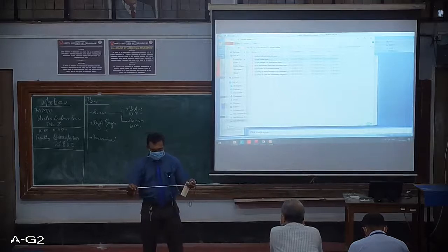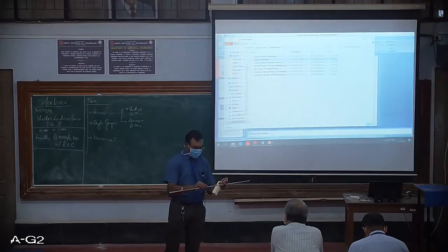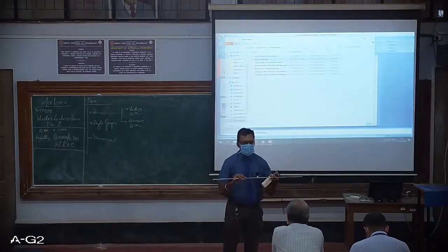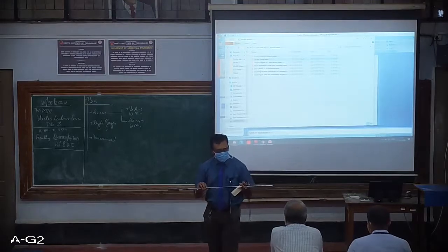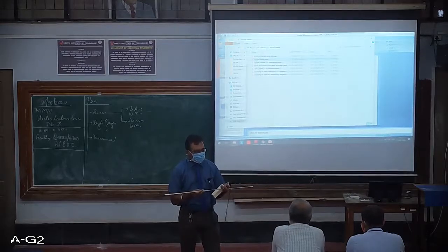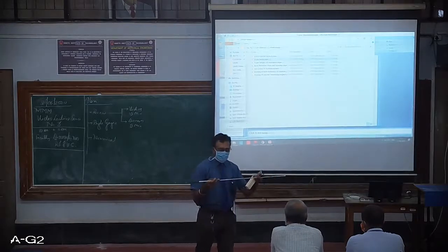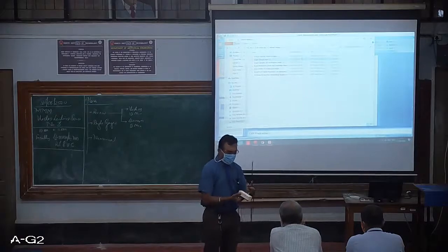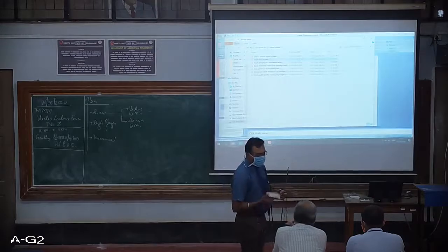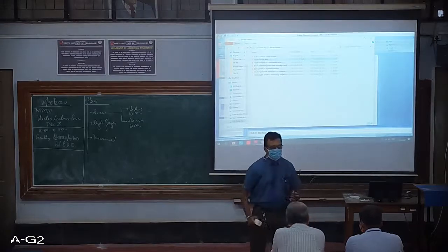So in our view, we should know, if someone asks in an examination, what is the IT grade for this stick that I have in my hand, which looks like a telescopic stick. I should know by feel roughly what the IT grade could be. Here I can say this should be around IT10 or IT7 or IT8. This is a super fine finish, but still I can say roughly. And if I hold this, this is nothing less than IT16.